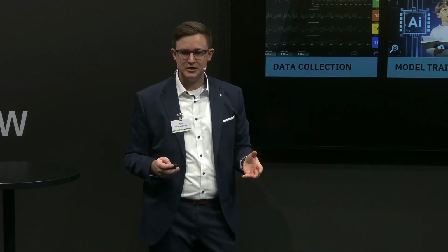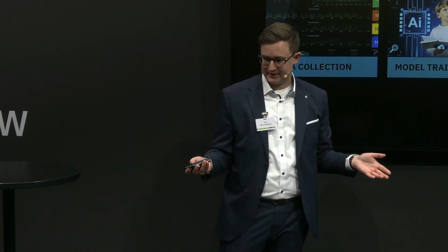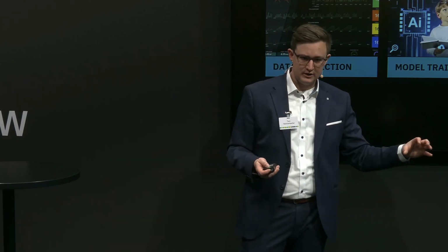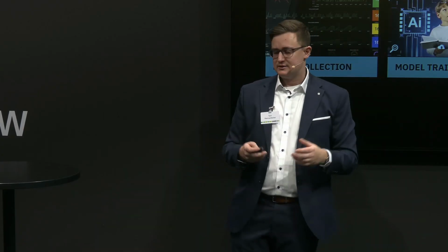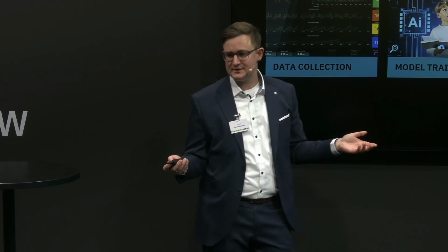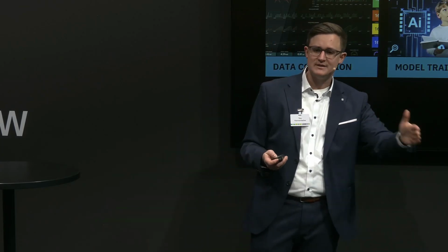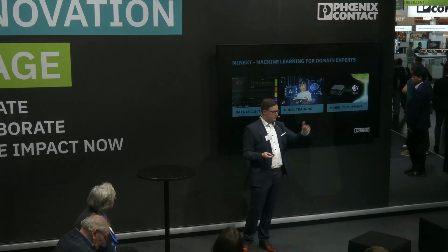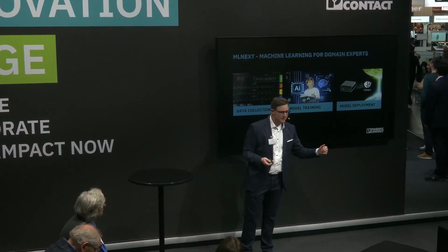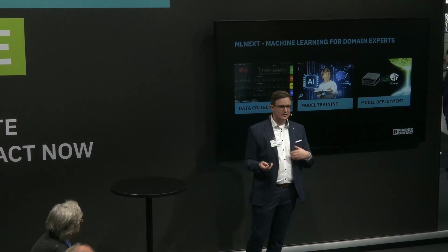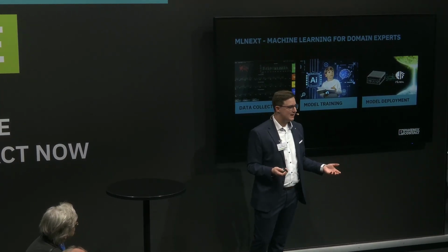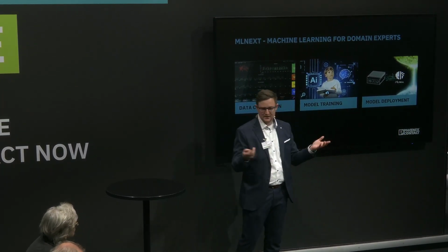Yeah, and for many applications, like automated quality control, for example, we really need fast response times. So the inference of the machine learning model, the data running through the machine learning model, cannot take longer than, for example, 500 milliseconds, because that is the normal frequency of my machine. If a machine produces a good every 500 milliseconds, or a production step is realized in 600 milliseconds, then the result of the AI cannot take 1.5 seconds, because I will be the limiting factor.